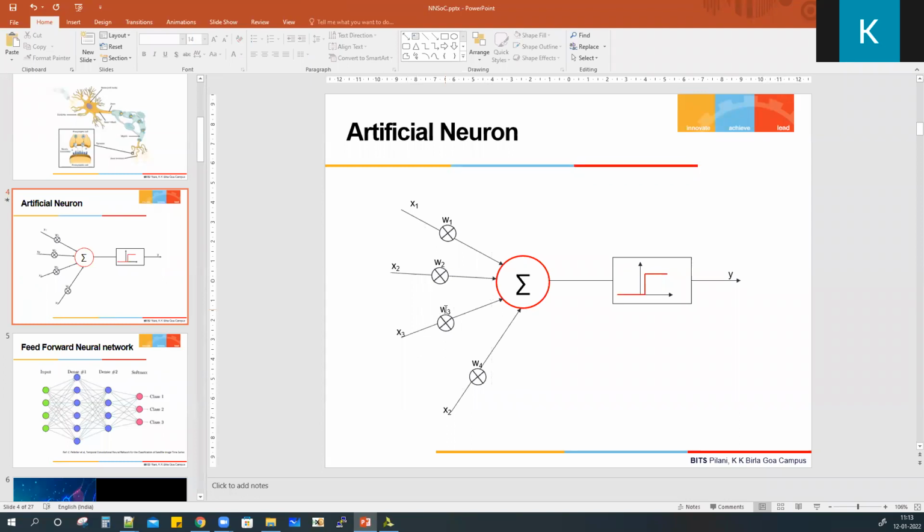In case of hardware, if it is zero, the tool might handle it. If it is non-zero, and I am doing a parallel multiplication, there is a definite advantage. But in this resource sharing architecture, whether there will be any real advantage, I don't think so. Anyway, I will have to use one multiplier per neuron, so the number of multipliers won't reduce. Latency also won't reduce. So in hardware, I will have to see how to exploit it.